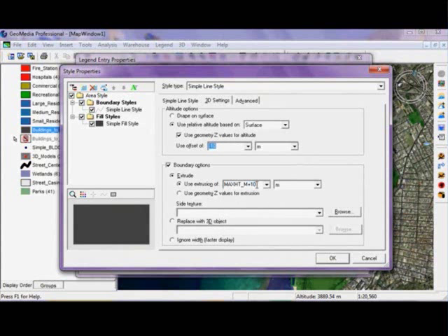You'll note that I've done a little best practice here that although I'm using my max height attribute to extrude the building, instead of just placing it on the surface, because I am in a hilly area, I've offset my building minus 10 meters, and then I've added 10 to the height. So I'm still maintaining my height accuracy, but I'm getting it to sink into the earth so I can account for any hilly terrain to get a nice fit for the building with the terrain.